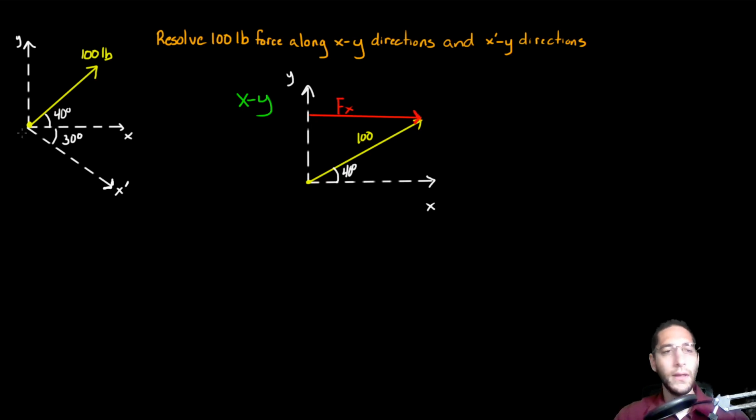And we're going to do the same thing with y. So we're going to put our pen here, draw a line down, and this green line is parallel to the y-axis, so this becomes my component of the force along the y direction. I'll call that Fy. Now we know with vectors I can rearrange them like so. So this right here is going to be Fy, and when I do this I create a parallelogram. And I can check this. Fx plus Fy gives me my resultant. Fy plus Fx also gives me my resultant.